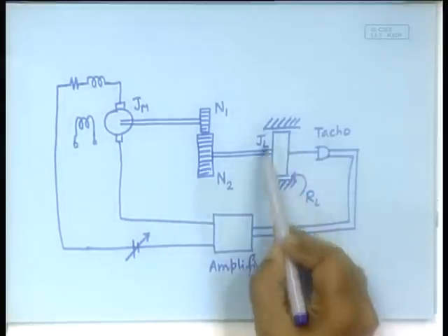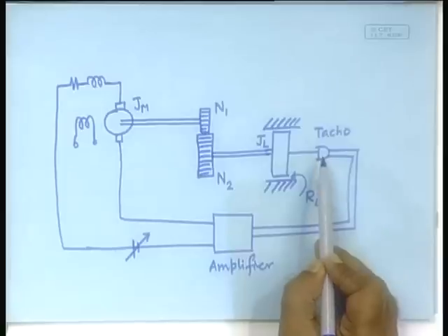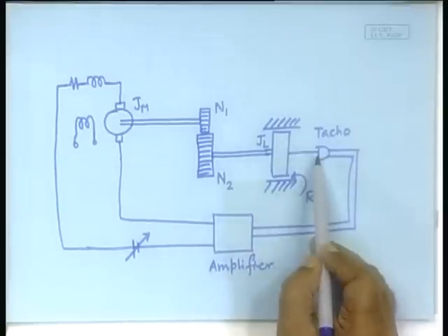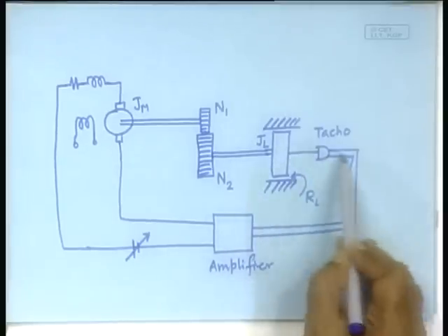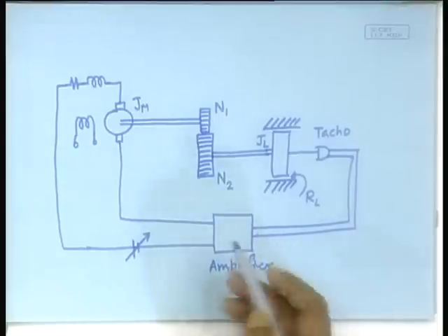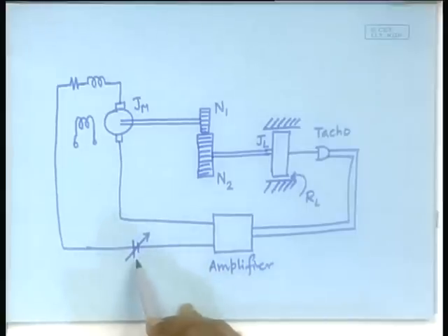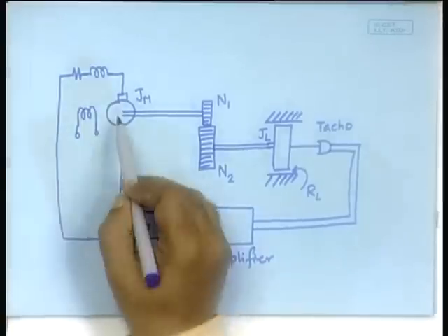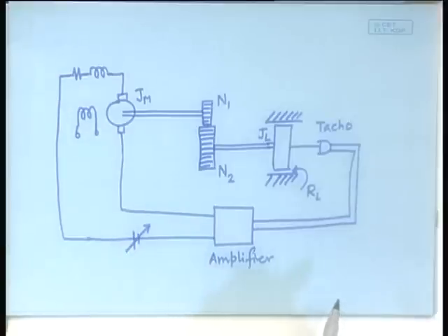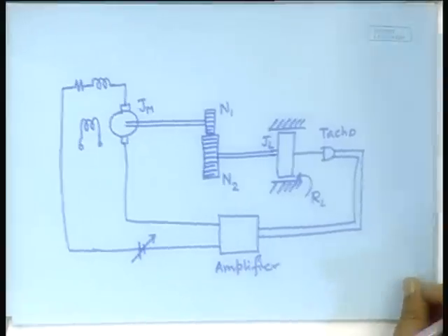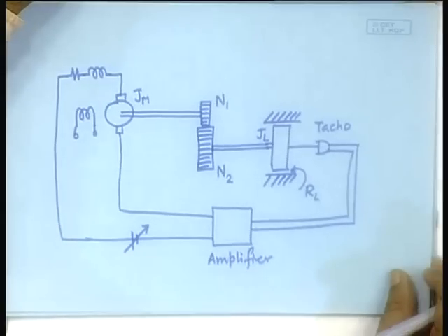So, you notice that here there is an observer, the tachometer is an observer, observer of what? The flow, it is a flow observer. The flow information is coming in, but the effort information is not coming. So, that will give rise to an activated bond. This is where the flow will be converted into an effort information to be added to the external voltage, right. So, that is what will give the input voltage here, clear. This is a very reasonably practical electromechanical system. What was the problem number? It would be 9.